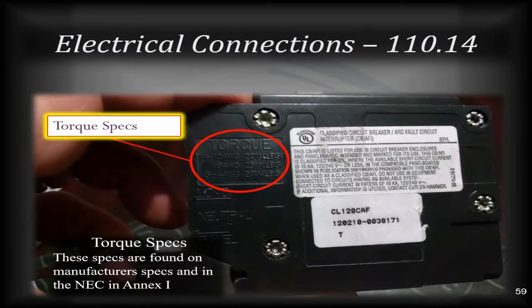Okay, first of all, we got torque specs. Same breaker, other side. We got torque specs that are stamped right on this device itself. And having those torque specs stamped right on there makes it so you'd really have to stretch to have an excuse to not actually torque your lugs.